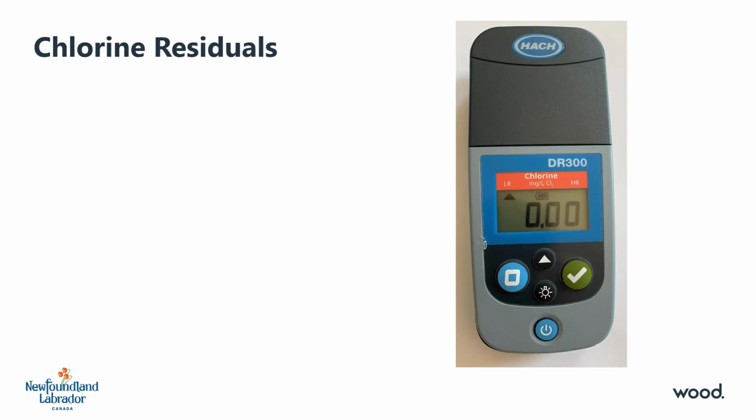Effective chlorine disinfection is confirmed by testing chlorine residuals throughout the distribution system. Chlorine residual is the concentration of chlorine remaining in the water after a given contact time in the distribution system. It is very important for system operators to test and record free and total chlorine residual readings at the start, middle, and dead ends of the distribution system every day. Chlorine residuals are often measured with a colorimeter. A training video on how to conduct chlorine residual testing is available on the Water Resources Management Division YouTube channel.